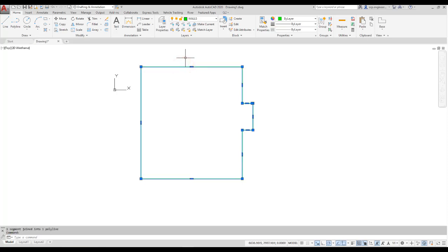polyline. I do. I can very quickly make the interior walls by choosing offset, writing in the offset distance of 150, that's the wall thickness, and I want to be on the inside of my wall. There I go. And I can continue to work through and put the other features on the model.